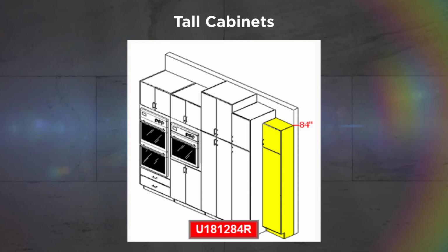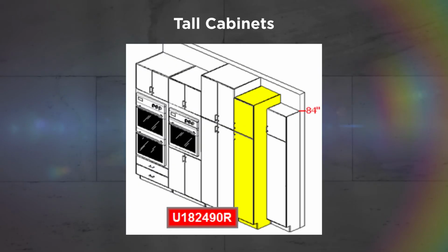The U18-1284R would represent a broom closet, 18 inches wide, 12 inches deep, and 84 inches high, and it's hinged on the right side. The 84-inch high cabinet would align perfectly with 30-inch wall cabinets. If the designer was using 30-inch high wall cabinets, the best height for a tall cabinet might be 90 inches.